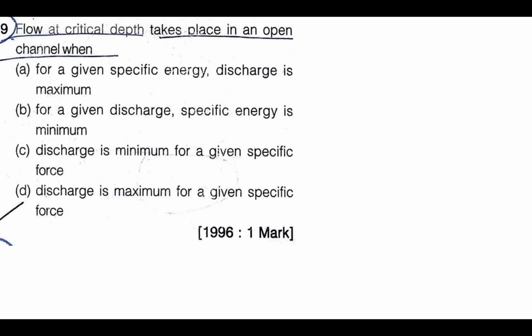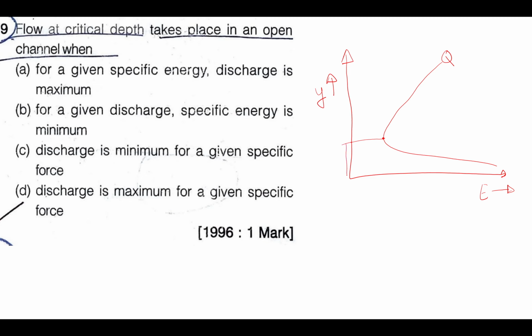Now moving ahead to the next question: flow at a critical depth takes place in an open channel when? Before moving to the options, let us draw the diagram of specific energy versus depth of flow, the specific energy diagram for a particular discharge. This depth is known as the critical depth, and this energy is known as the critical energy.